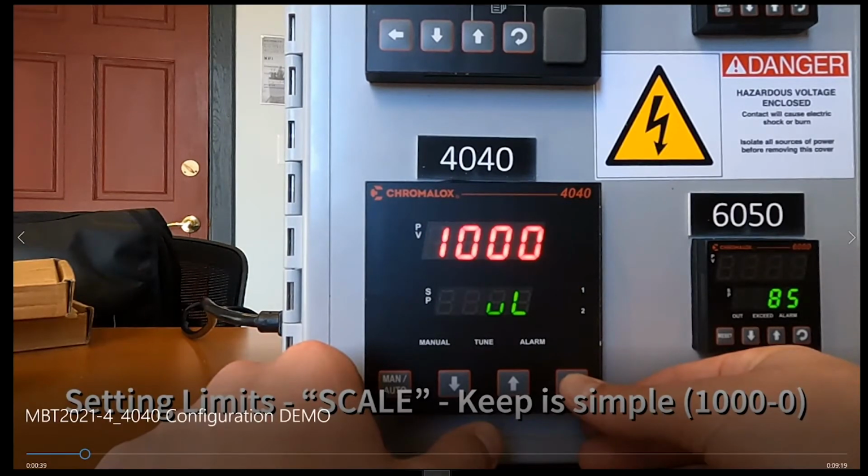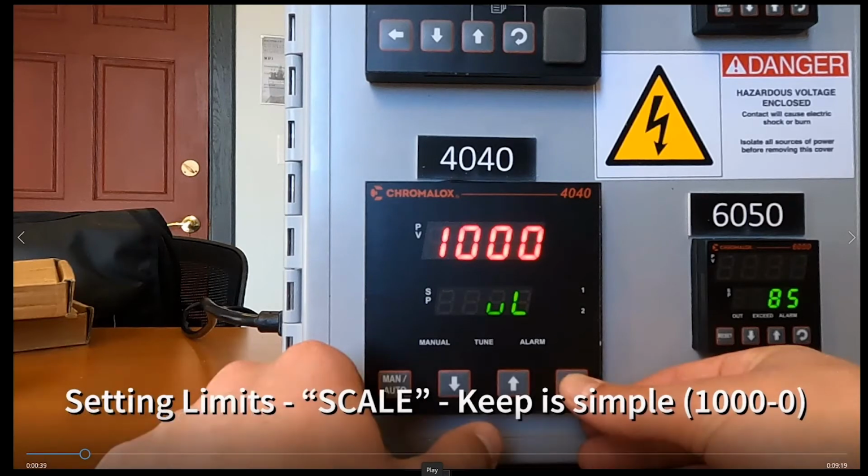So with the scale range upper and lower limits, I know it's a very confusing topic, but there's really kind of two things. So we recommend setting it to 1000 for the upper limit and 0 for the lower limit. If you are using an analog input to this controller, it should automatically default to that.